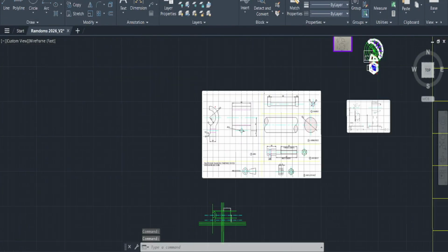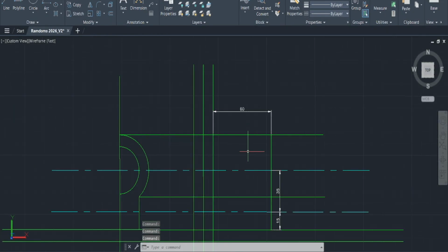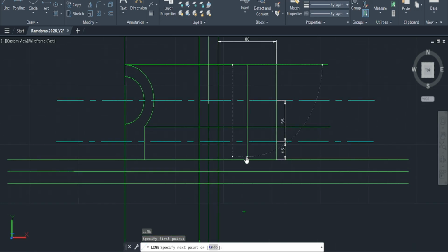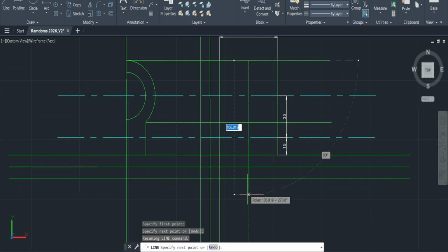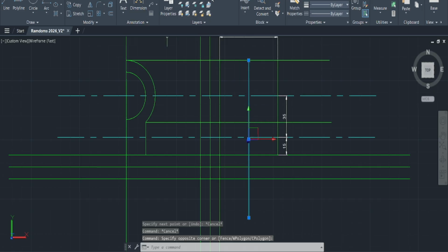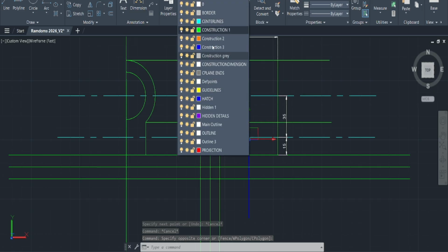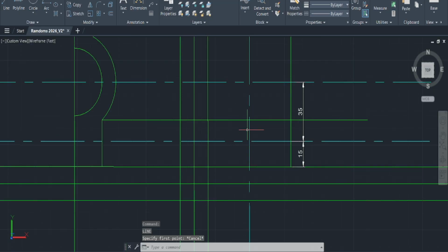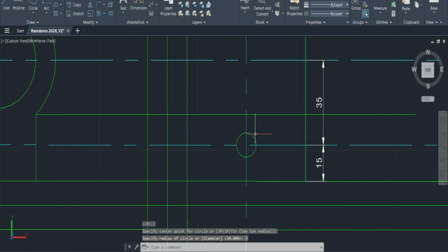Alright, so we're just gonna come back down here, we're gonna look for the center. I'm just gonna use my snap to pull that center line straight down. Just gonna leave it here, turn that into an actual center line. Awesome. Enter, escape. Then I'm gonna go C, enter. So since the diameter is 10, I'm actually just gonna go a radius of 5, enter,